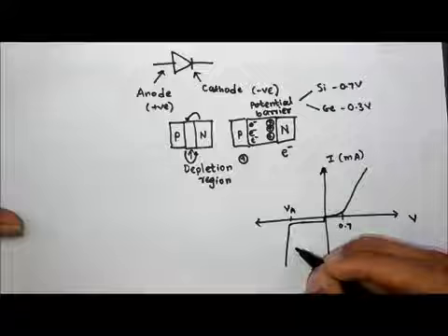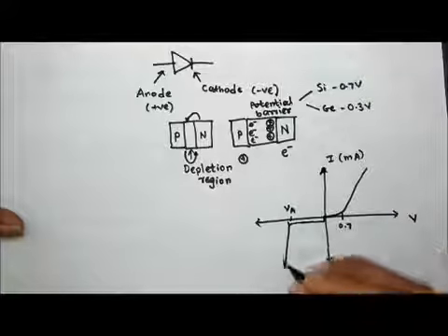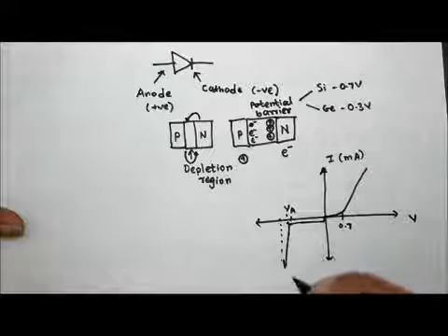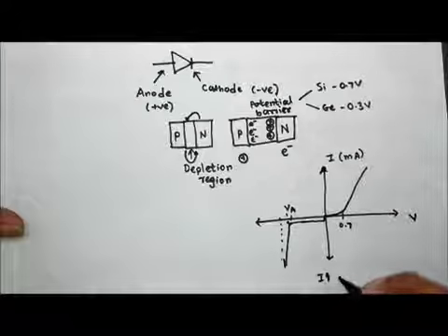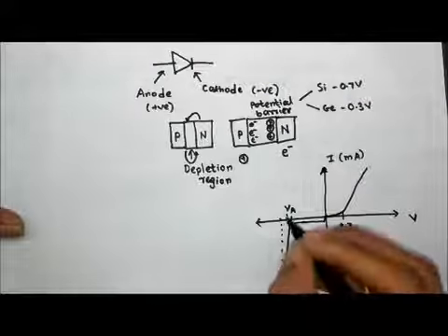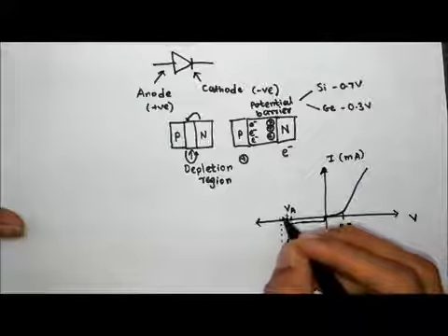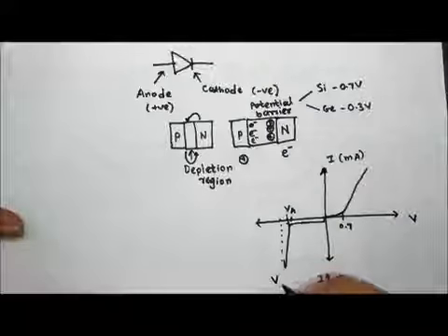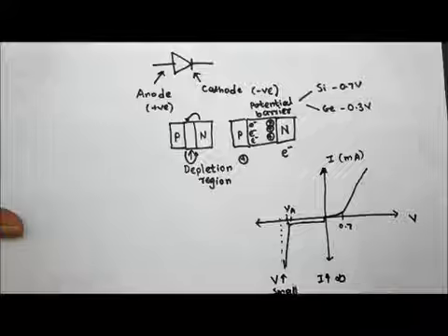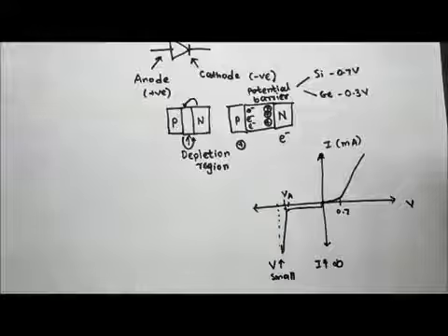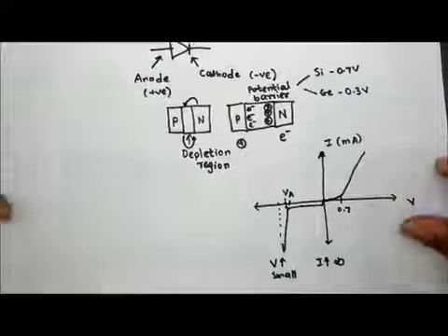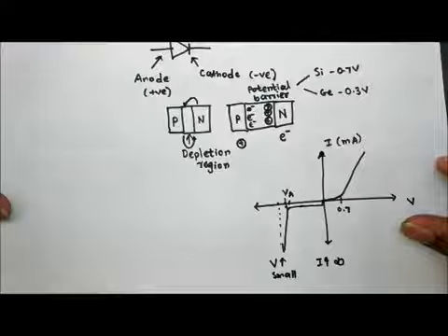So what happens here is, if you observe this region, current is increasing by infinity. It's almost infinite, right? While there is a very small difference in voltage here. So the difference in voltage is small while current is increasing infinite times, which means even if you change the voltage a bit, the current increases steeply, and this causes heating in a diode.